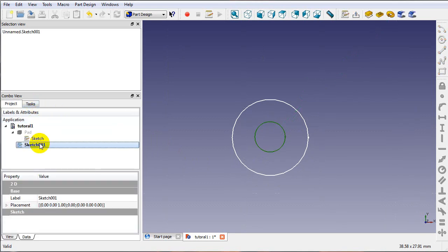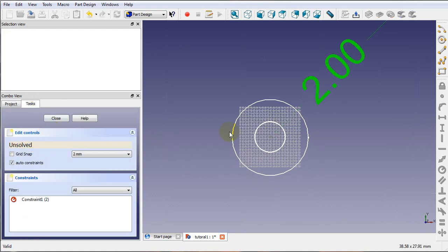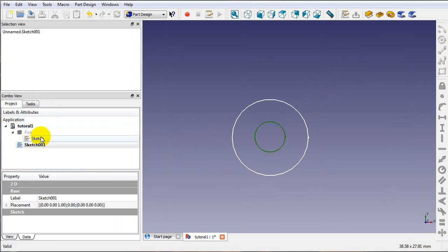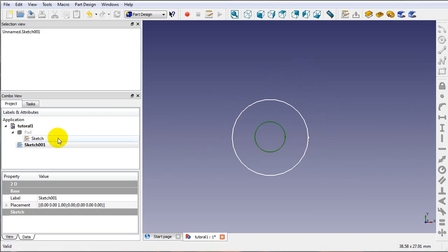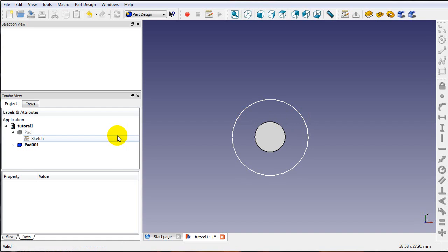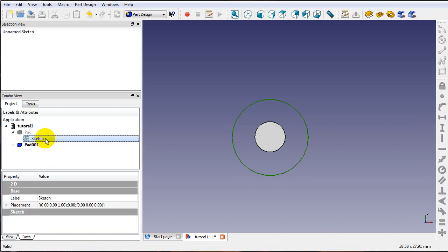and on clicking on sketch 1, which actually if you double click, you notice it goes back into the sketch, so we close that. So you can always get back into your original sketch anytime you want. You can view other sketches and actually reference off of them to create new sketches just by making them appear using the space bar or making them disappear. In this case, we want sketch 1. We want to pad it, and you'll notice a new pad appears. Let's go back to our old sketch, click on it, and then hit spacebar to make it disappear because we don't need it.